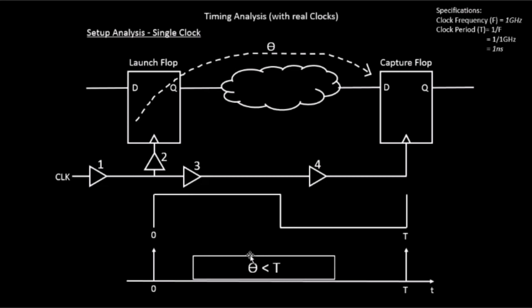Okay, we have to come up with some equation that says that if that particular equation is being met, your system will work at 1 gigahertz. Basically, we have to finally conclude that this particular system has to work at 1 gigahertz. And what are those equations, what are those conditions in the presence of this particular clock tree? And eventually we will be tuning the clock tree in such a way and see what can go wrong. So let us first start with the basic equation.